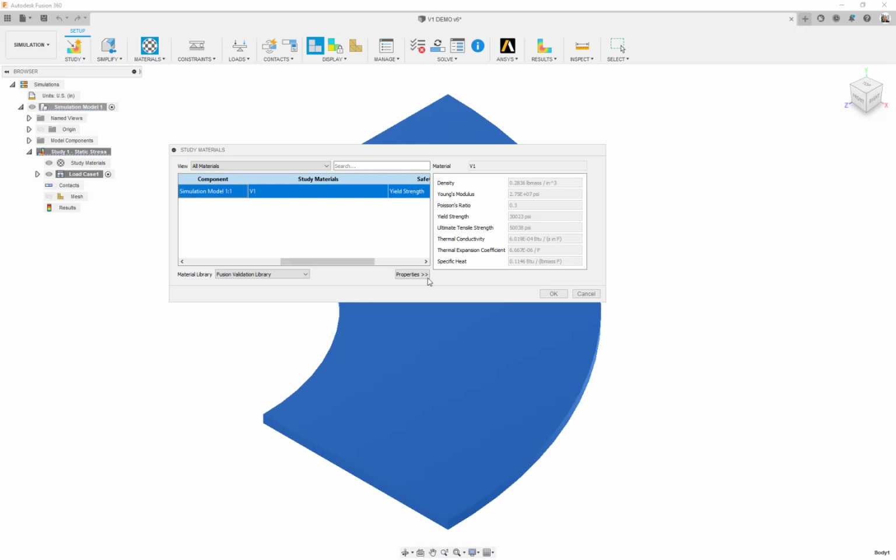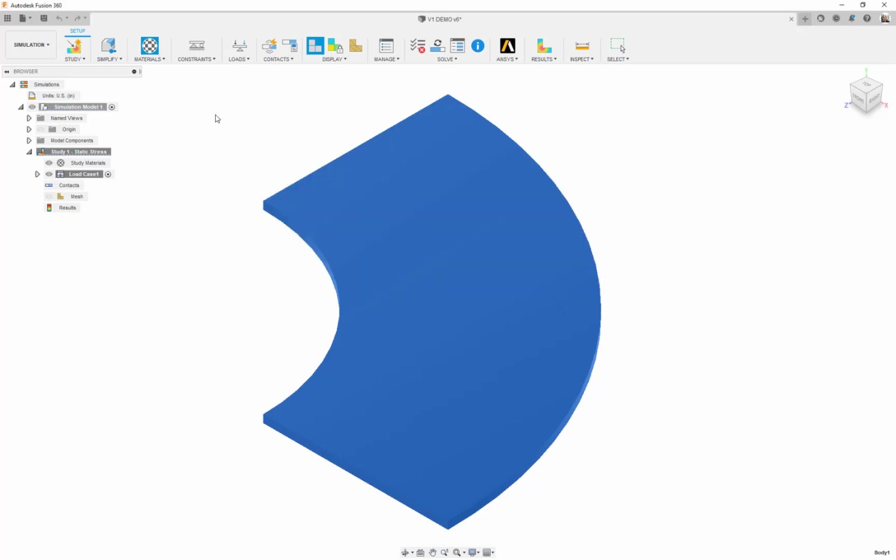So let me select that material from the list, and now you can see there's the Young's modulus that the problem description had, 27.5 E6 or 2.75 E7. Poisson's ratio is 0.3. The rest of the properties are here because I chose that steel material, and then I just edited the material properties that I needed to edit, primarily Young's modulus. So we'll say OK to that.